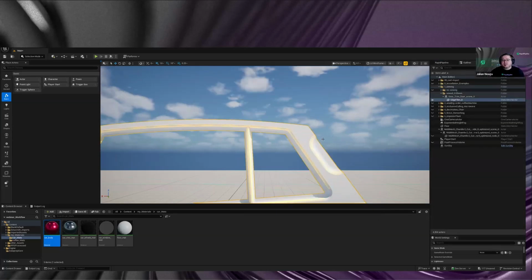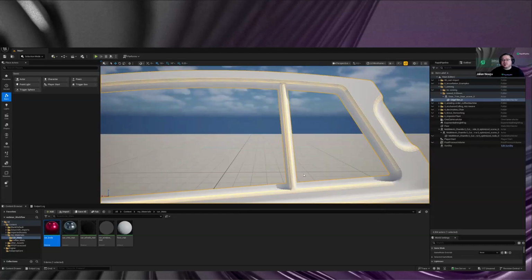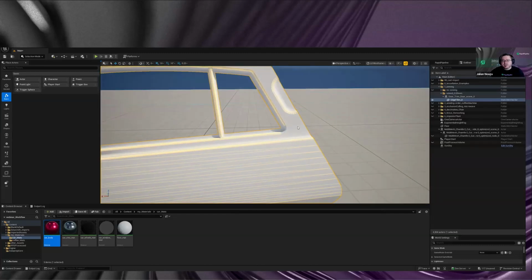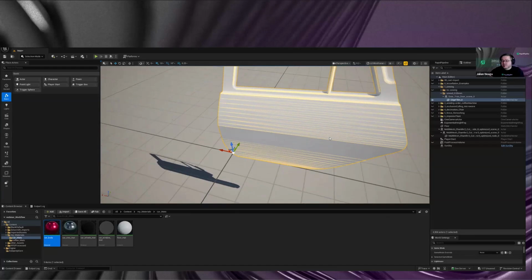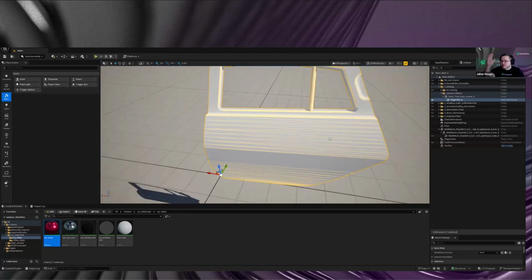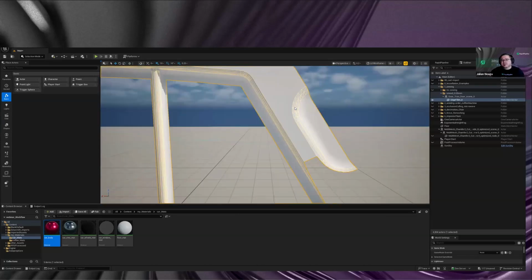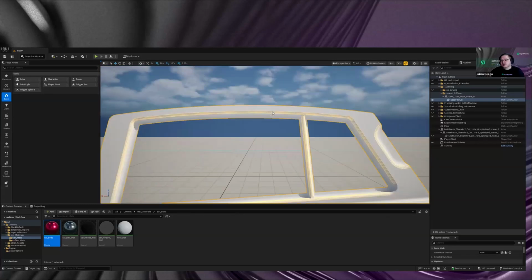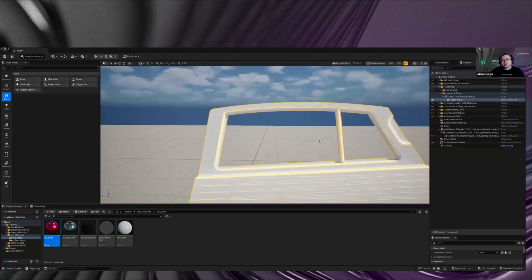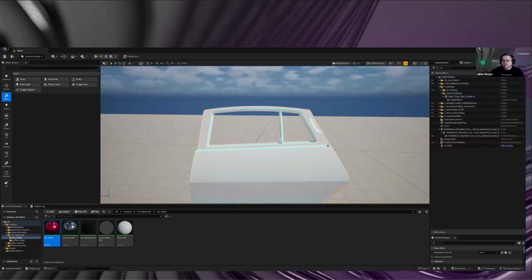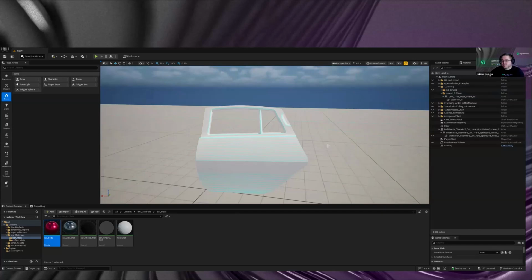And we still have differences in the topology, as you can see here, right? Like very flat surfaces with a low resolution. And again, we could steer this, as I said before, a little bit with the maximum edge length and things like that. So you could actually throw an edge loop here in the middle. But you will get the vertices all lined up correctly and merged, and then you can run further optimizations on it, like decimation, without having the mesh falling apart completely. So this can be really helpful for certain solids with a lot of patches on the CAD ingestion.